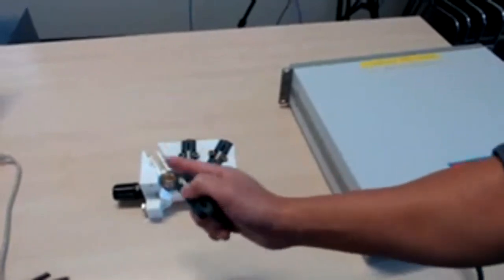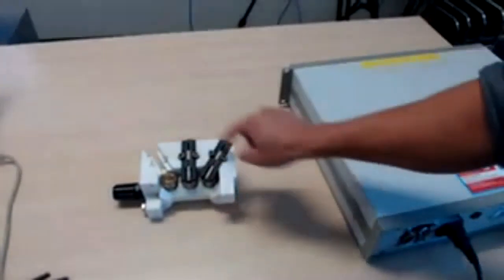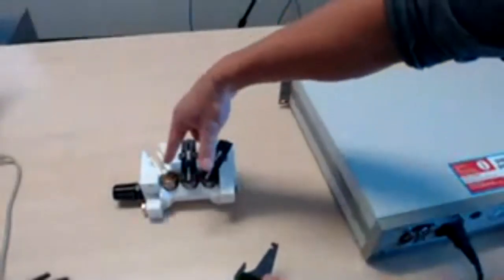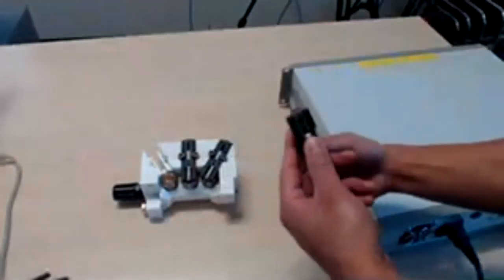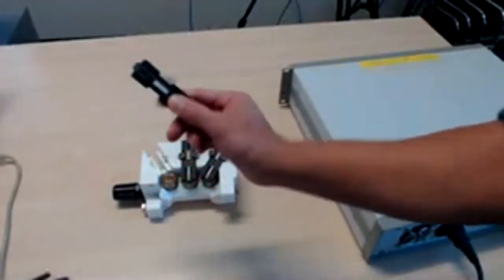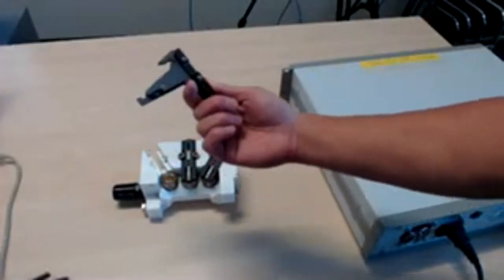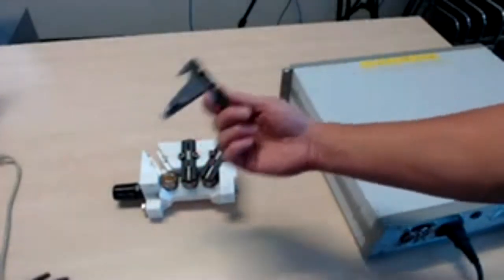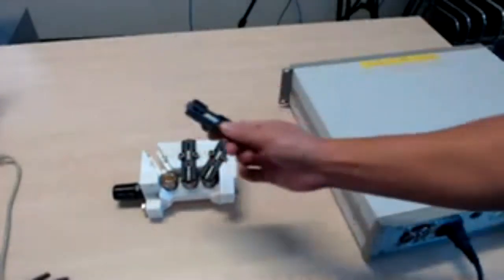These latches can be easily swapped out. So say I'm having a problem with latch number 1. A good troubleshooting method is to take out latch number 1 that is having the problem and swap it out with, say, latch number 2 or 3. See if the problem moves with the latch that you just took out, or if the problem is always stuck in this position right here. That's a really quick and easy way. I would also recommend having a few spare latches on hand on your research vessel. In the event that one of them gets damaged, again, you can easily swap them out here.